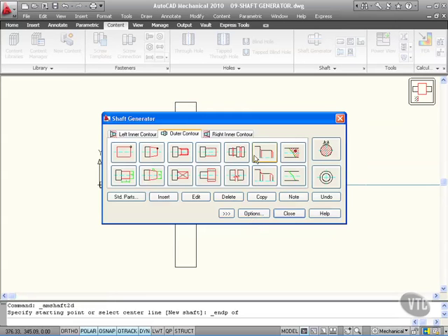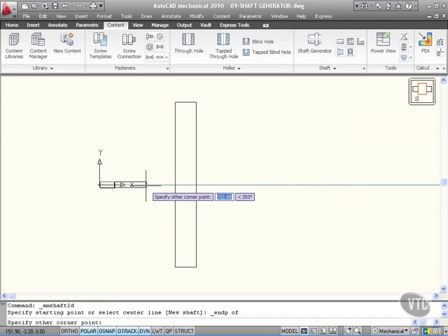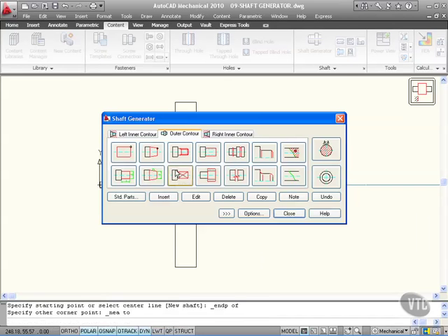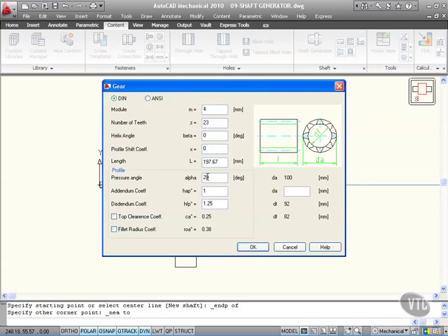And then, as you can see, I can pick something that I want to add. I could just add a standard cylinder, like this, and then specify the other corner point. So as I come out there, I'll do a shift and a right click and go for nearest, and I'll maybe drop it up to there. And I'm just adding bits as I go. So all I'm doing now, I'll pick that one there.